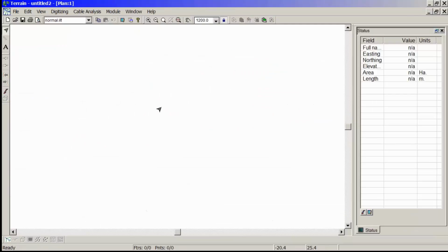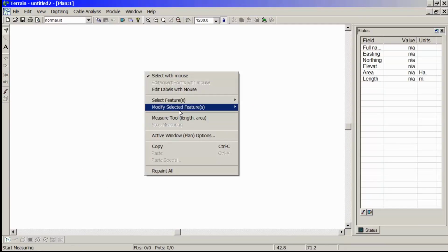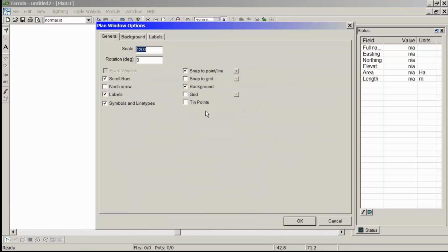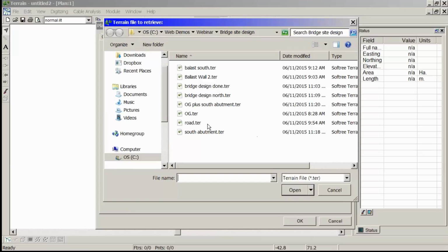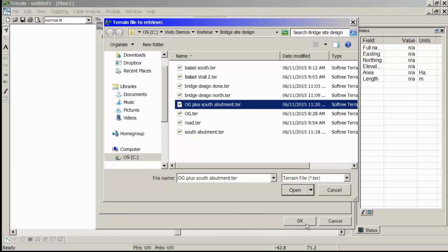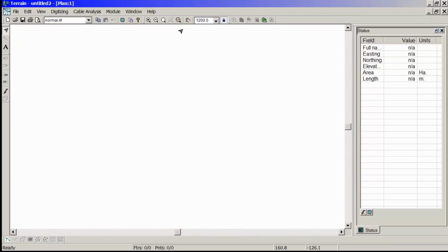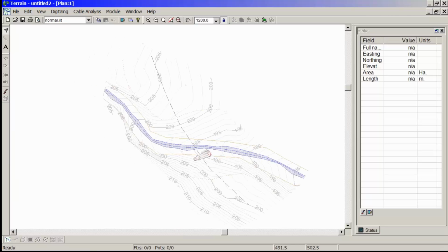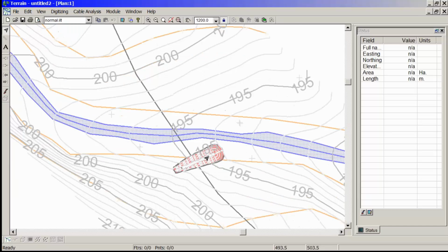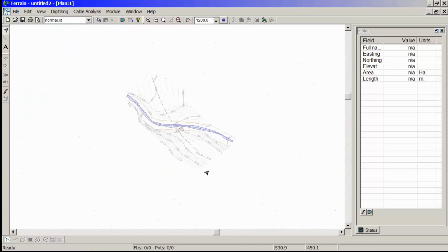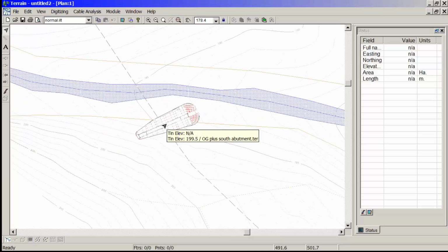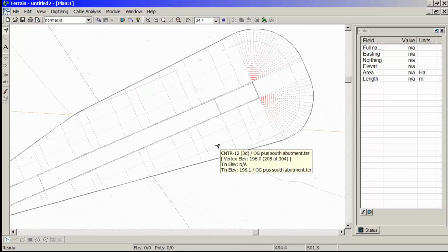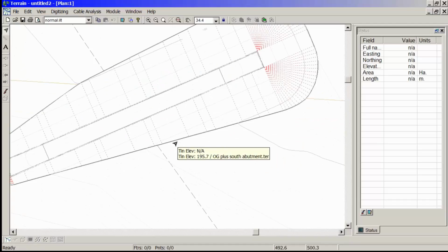Start again with the background being the one that I just had, the ballast wall and my original ground. So that's going to be my starting background to draw my road. Unlock my scale so that I can work with it a little bit better, and the labels don't look too large. Okay, now let's draw a feature.